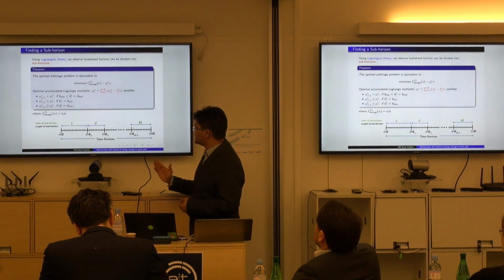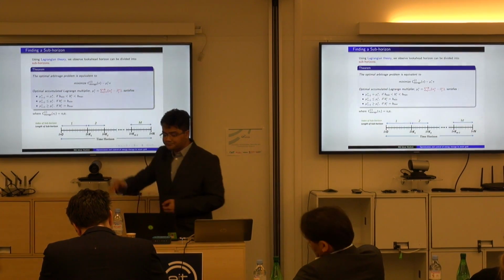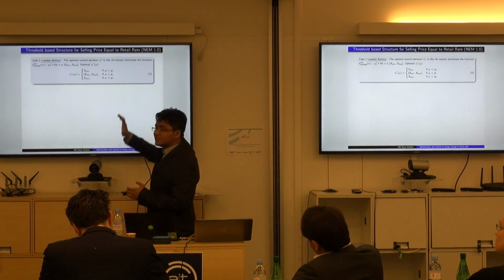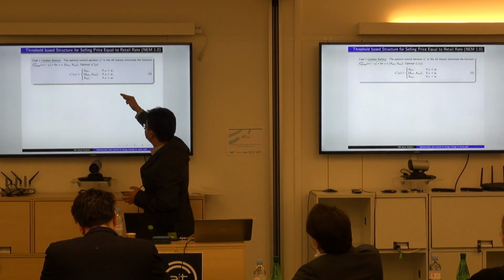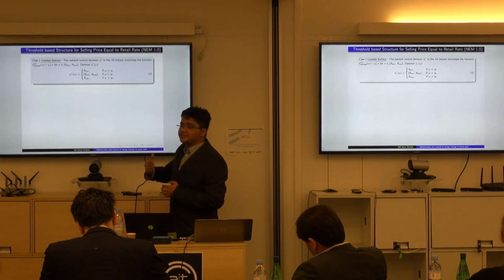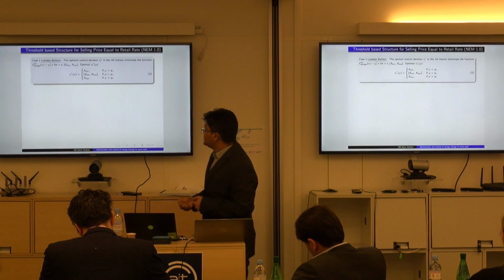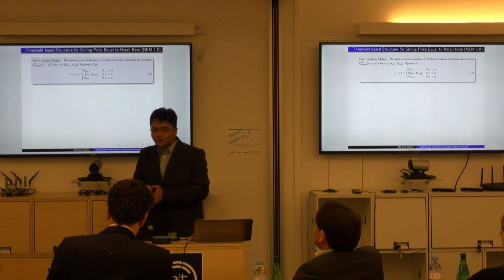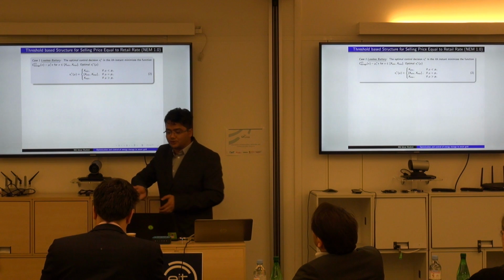I'll demonstrate that with an example, but the next level is, with this cost function, how do we minimize it for each time? Consider a lossless battery in which there is no charging and discharging efficiency. In that case, I'll have 3 levels based on my price level. So this cost function is minimized, and these are the states. What we see is, whenever mu is equal to the price at that time instant, then we have an envelope-like structure. We have a lower bound and an upper bound. This part does not give us a fixed solution, but gives us an envelope of solutions possible.